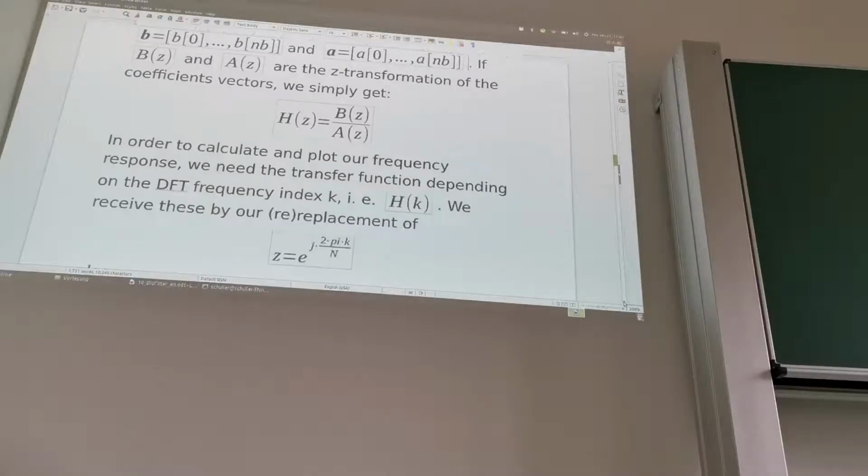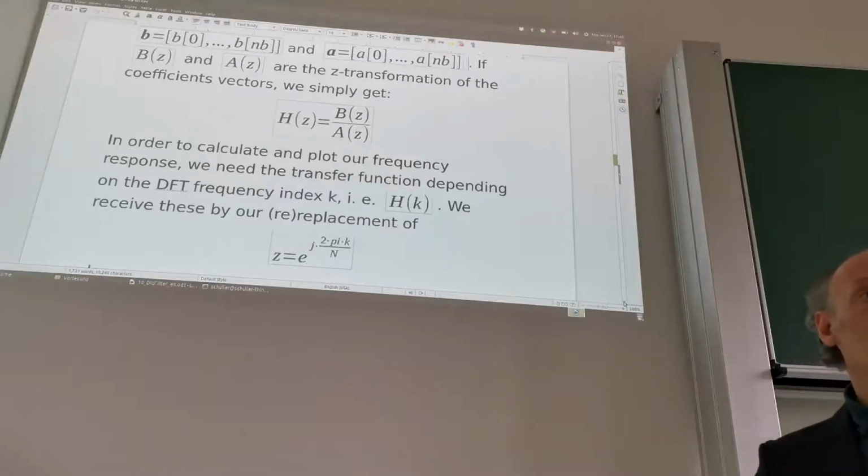And those poles don't have to live on the unit circle, they can be anywhere in the complex plane, and the location gives us a lot of insight about the properties of this transfer function. So that's another reason why the Z transform is so useful, because we can analyze theoretically the properties by looking at the zeros of those two polynomials and their location.